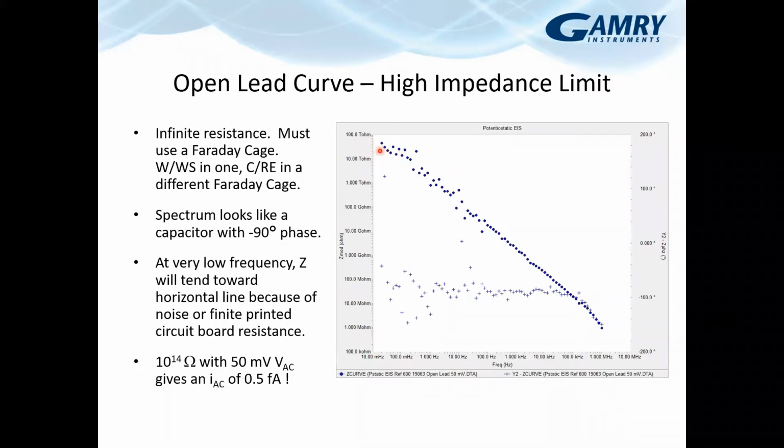For some systems, if there's not as good a current sensitivity, you will start to see it roll over at lower and lower values. And that's where that IE range comes over. We don't see it here because we're not going to low enough frequencies, and the system can make accurate measurements at a teraohm, and we haven't hit 100 teraohms here yet.